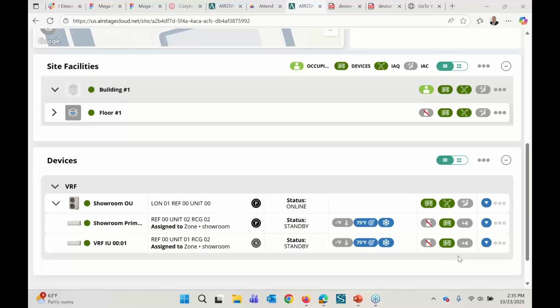They're going to look here to see what other questions we have. So first question: no power cycle requirements for the VRF, or is it the same for AIRSTAGE H? With AIRSTAGE H, you do not have the amount of remote configuration that you can do with the VRF. With AIRSTAGE H, you don't have as many of the remote function settings that you can program. So it's really not as much of an issue on the AIRSTAGE H.